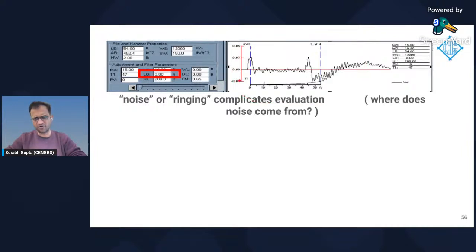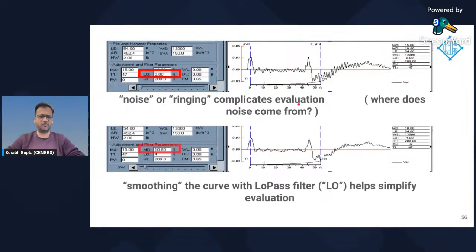So, of course, we've collected the data. Now the question is, is this data still usable? Do I have to reject it? Do I have to go back and retest? Or can I still use this file? The answer in this case was yes. There is something which we can do to smoothen this high frequency ringing that you see in your PIT data. That something is known as the low pass filter.